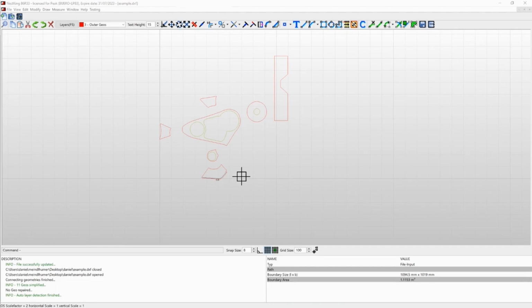Actually, I've just recognized this week when preparing for this presentation today, there is not just one offset to be generated for all these splices here, especially if we consider that we also have to generate the whole stack up with, in the best case, just 4 to 5 layers of material. So we are talking in this case about 20 to 25 offsets per layer and 100 offsets for the whole part. And this is just a tiny part of the whole gearbox.